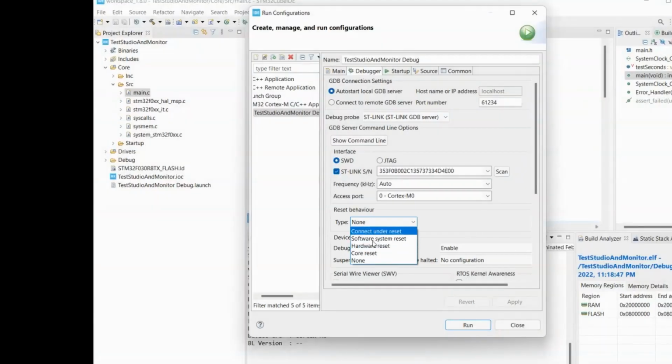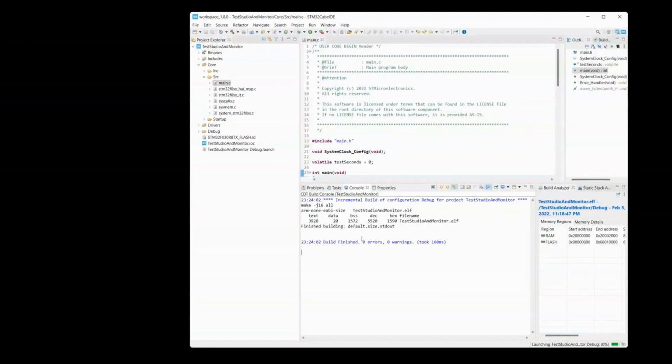If you are having problems connecting to the target, in this case the microcontroller, then make sure that the connections to the microcontroller are correct and that they're solid. You'll have messages like cannot erase memory or cannot connect to target. Those are all signs of a bad connection from the microcontroller to the ST-Link V2 programmer.